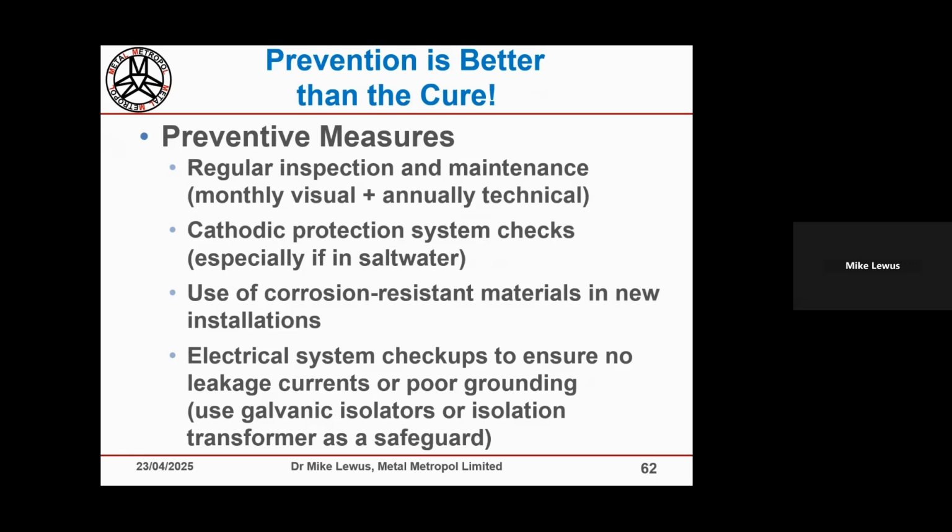Because at the end of the day, before you even think about what anodes you're putting on, the first thing you need to know is what is the surface area of metal you're trying to protect, and what are those metals? So the reason I asked is the owner of this boat couldn't understand why the boat was falling asunder and had to go through a major refit. It never had anodes on it.